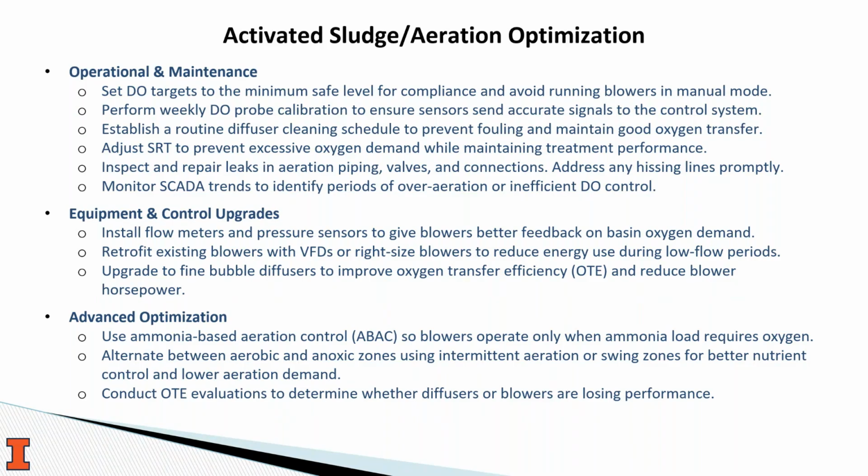Adjusting solids retention time can also help prevent excessive oxygen demand, and inspecting aeration piping and valves for leaks can prevent blowers from working harder than needed. And again, monitoring SCADA trends can help operators identify periods of over aeration or maybe inefficient DO control.